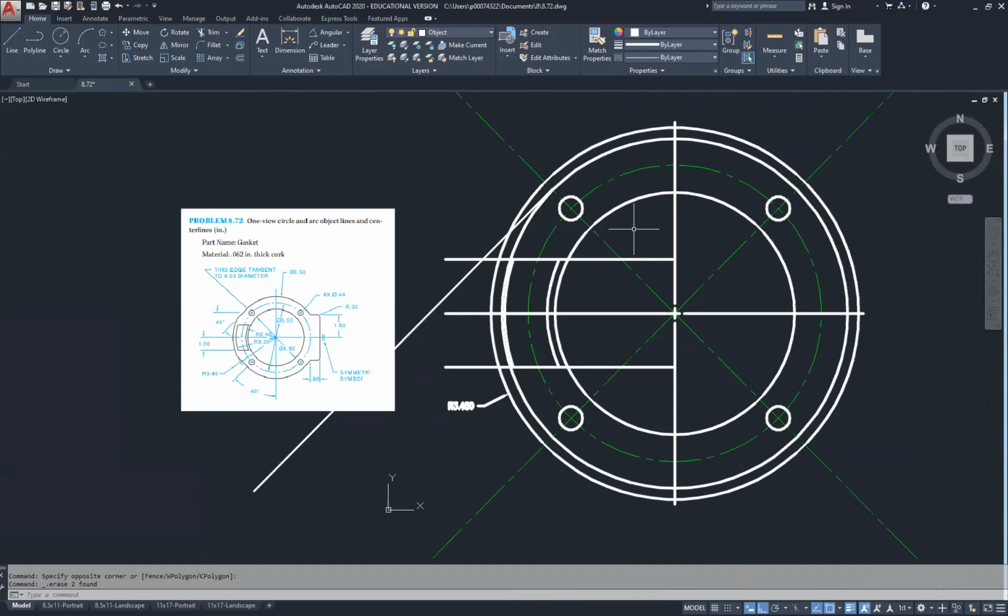All right. I'm going to take this line that I have here. I'm going to mirror it. Choose the mirror command again, picking the center of the circle and moving it to the right. Selecting on this spot here. I'm going to hit Enter key. Now I have my two tangencies. I'm going to use them as the cutting plane. So I'm going to use trim, selecting 1 and 2.